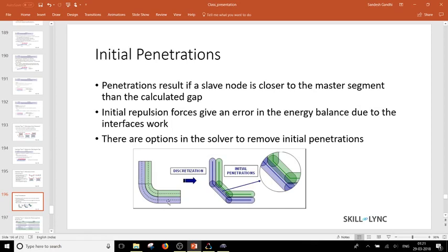Now in the picture itself, it is very much clear that there are two meeting parts which are connecting on a fillet as well. Because of the discretization, while meshing, I mesh only one element over here instead of two. Now if I have only one element, I see that even this fillet is being meshed with one element. Because of the definition of the gap itself, it creates a zone around both the components, and this is the exact area where it says that, hey, there is some penetration inside the model at the beginning itself.